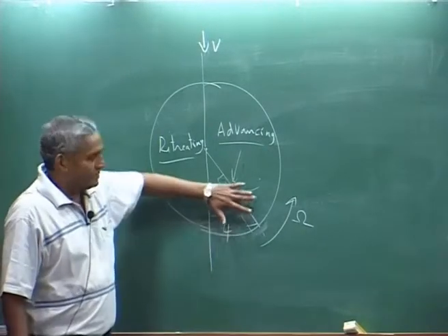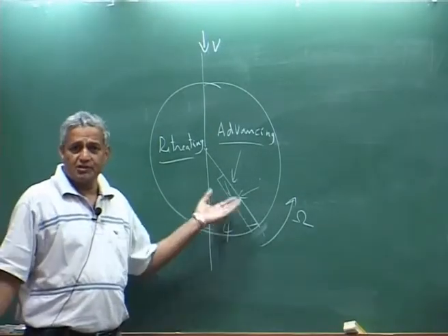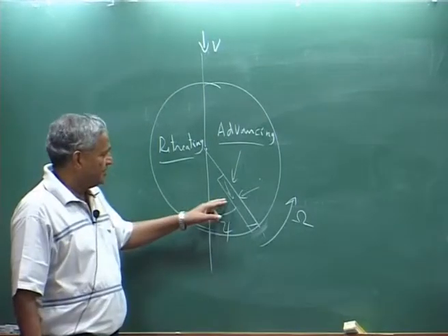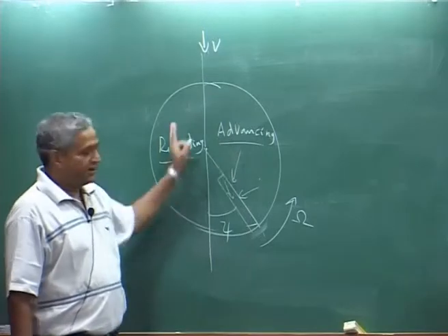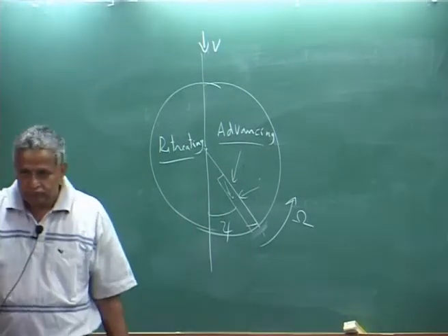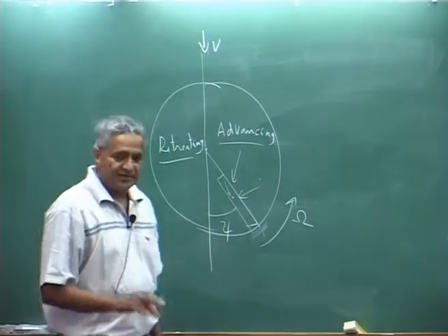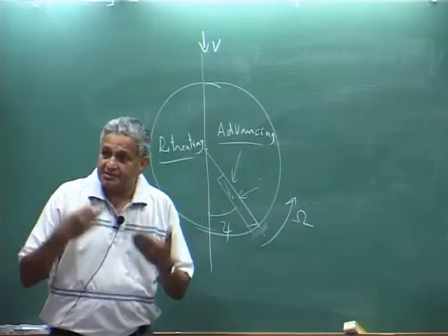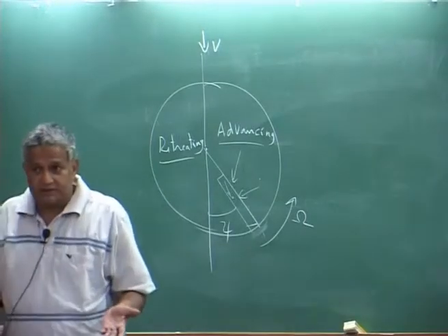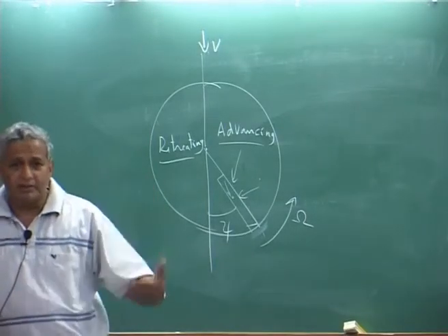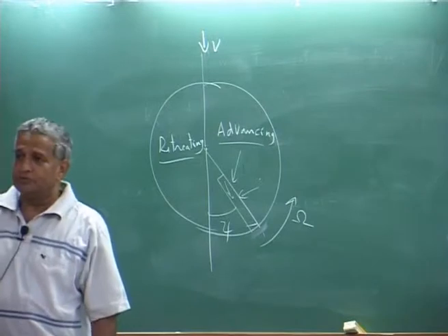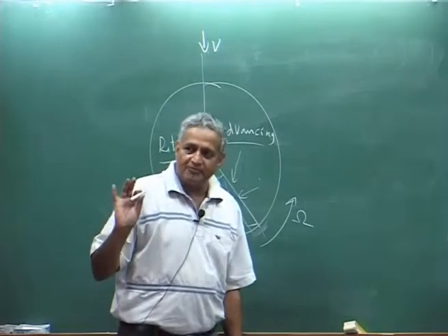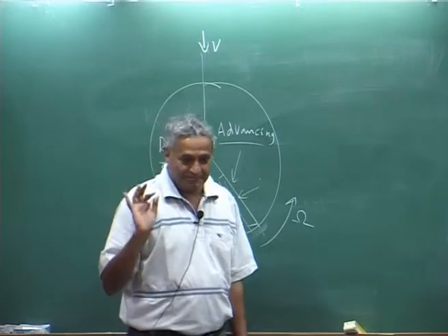Now you know that this blade is going to experience loads, and we will consider very simplistically that this velocity varies as sin psi. Now the lift is going to be, because it is a square of the velocity, a harmonic variation of lift, so the blade is going to go up and down. Let us consider only the flapping motion, flap.